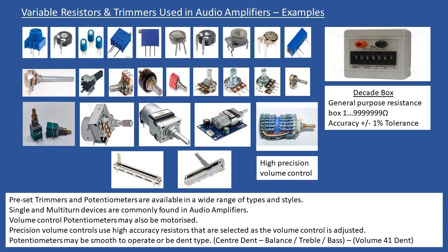Now, the design of these again is very, very broad, so it could be a different shaft length, it could be a D-type shaft, it could be a split knurl type shaft. The range is huge, so trying to source these is challenging at best. Okay, and for myself, because I've been doing this a long time, I have a broad range of potentiometers, but even now, many years on, I still get amplifiers that come into the workshop, and trying to source these potentiometers is not easy.